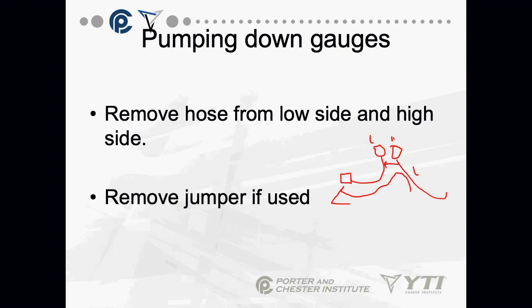That's exactly the issue. Your vans, trucks, whatever you're issued, on a peak summer day is going to get pretty hot. I mean, we hear about it every year when people leave pets and kids in cars. But the reality is that as soon as your gauges are sealed into that truck or car or van, that inside temperature is going to go up. That 60 psi of vapor that you have in those gauges could easily peak out at over 300 psi by the time you come back and grab those gauges. So you've got to be very, very careful with those gauges.